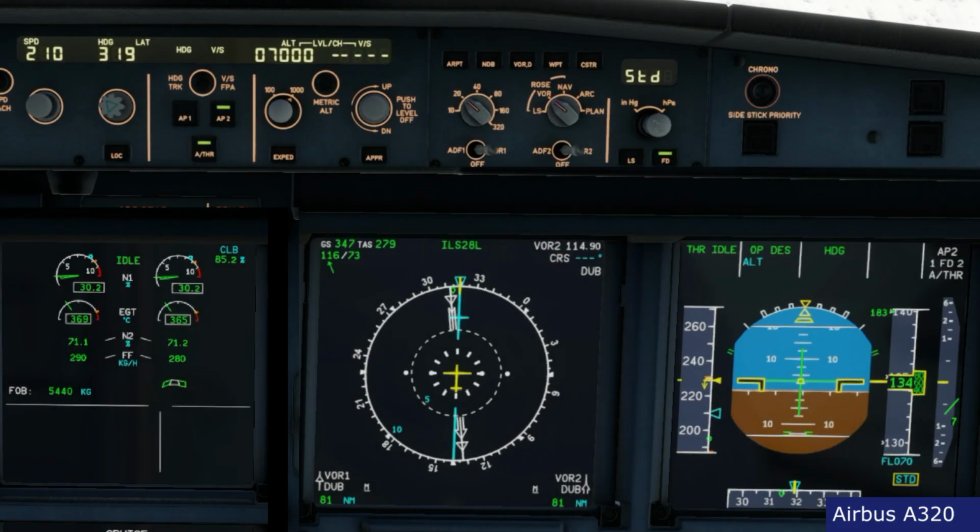So you see that in order to have a continuous deceleration, the aircraft needed to reduce the vertical speed. Now we are at 700 feet per minute. The speed is approaching the selected speed of 210 knots. As we reach 210 knots, same thing, we're going to have a small increase in the rate, because this time we're going to use again the potential energy, so the altitude, in order to keep constant speed. At the moment we are trading off speed in order to match 210 knots, so we're losing some kinetic energy, and in order to lose this kinetic energy we have to reduce the loss of potential energy.